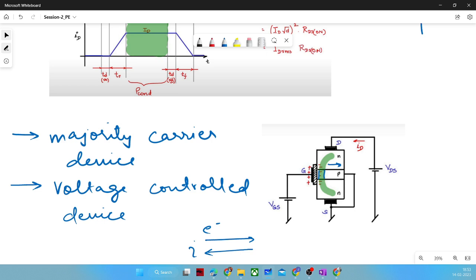And it is being controlled by the voltage you are applying. Once this applied voltage surpasses the threshold limit, that is VGS(th), every device has its own different threshold value. When that value is surpassed, it means the channel is created, and it has been depleted by the amount required to conduct the flow of current, and now you can flow. So that's why you see this kind of characteristics, right?